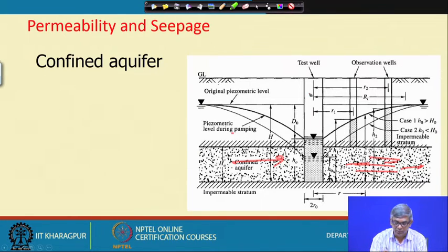It is not necessary that the water stays in between, maybe water is discharging from here. So, if I make a borehole from here, then whatever water level it shows in this borehole, that is the equivalent water level you can imagine. Suppose I make a borehole and the water level comes somewhere here, that is the initial water table to be assumed, and then by pumping, suppose I have to bring it down somewhere, or I want to find out the permeability value.